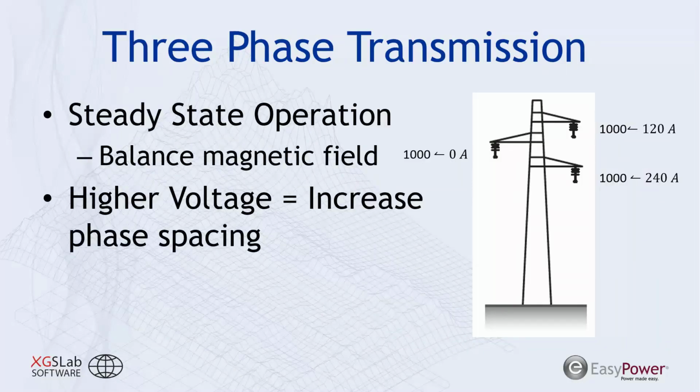And because we're talking about AC interference as it relates from a transmission line to other objects nearby, in our power system we use three-phase balanced systems. And that means that we're going to have balanced current on each of our phases, which results in a balanced magnetic field. But the difference is that the magnetic field strength is going to be dependent on its relationship or its distance from each phase conductor.